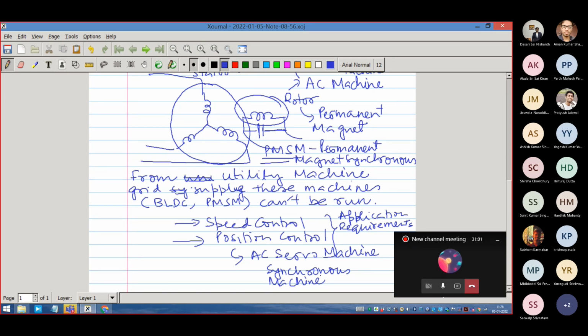So torque is an independent variable. Torque doesn't depend upon speed. Many people have this misunderstanding that torque is dependent on speed. Machine torque is not dependent on speed. I can generate torque at 10 rpm, and I can generate the same torque at 100 rpm. I should have no problem. So in order to develop this flexibility, because essentially the motor is capable of giving torque, torque is T_D, the torque developed by the machine.